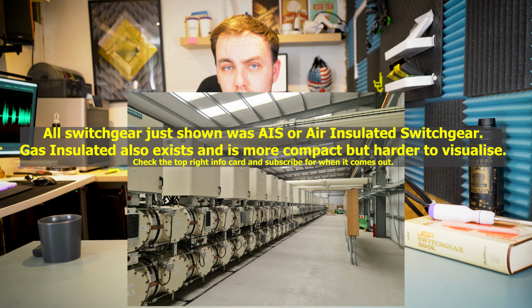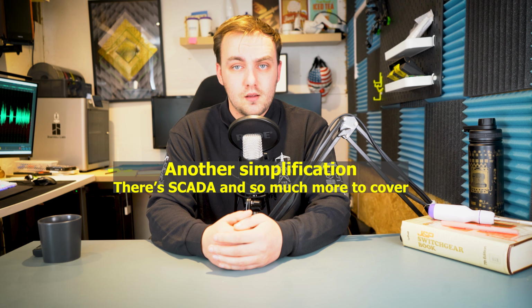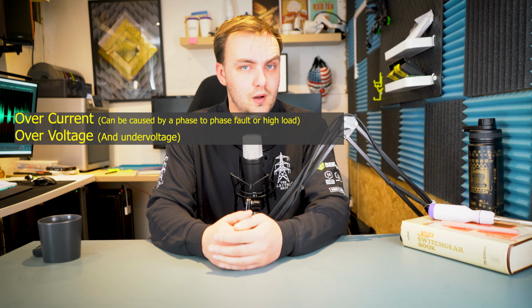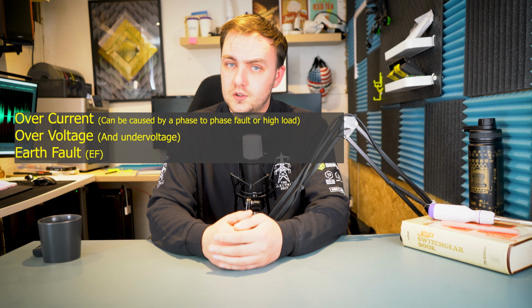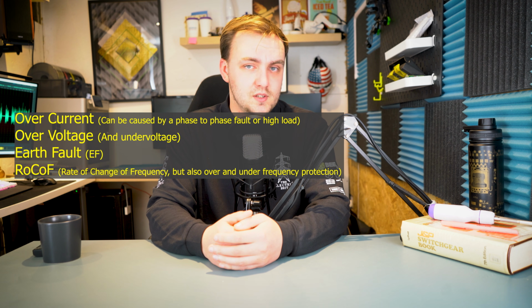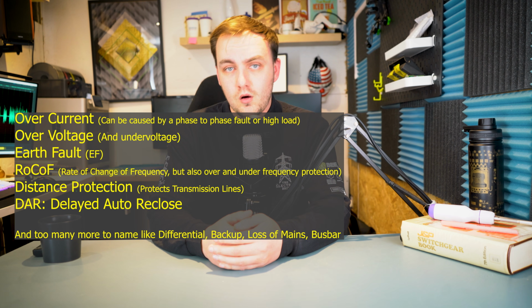And a final component, which is control and protection, which allows us to remotely monitor the network, control the switchgear and automatically protect it in a variety of fault conditions, like overcurrent when current gets too high, overvoltage when voltage gets too high, for example from a lightning strike, earth fault like when something touches an overhead line like a tree, or rock off like I described in my previous video here on blackouts, as well as a host of other amazing technical functions like distance protection and DAR, which I'll explore more in a dedicated video.